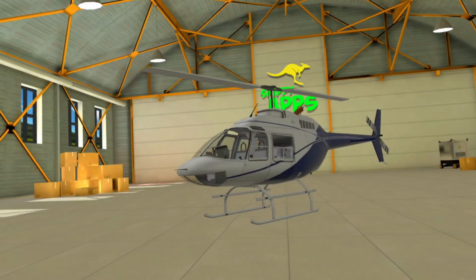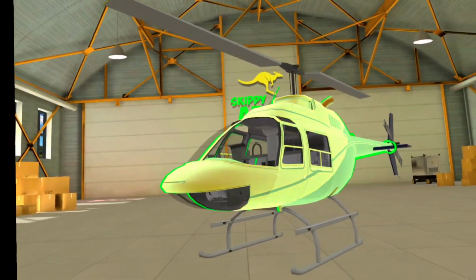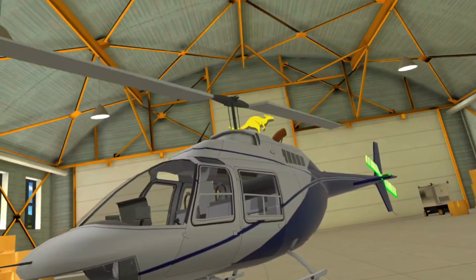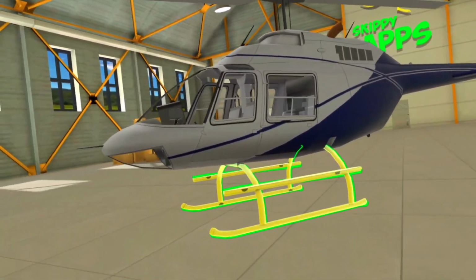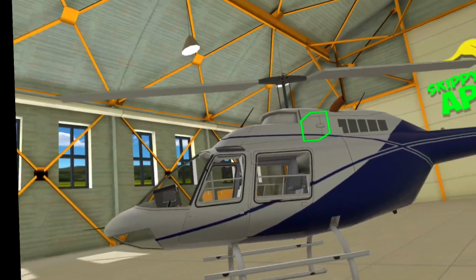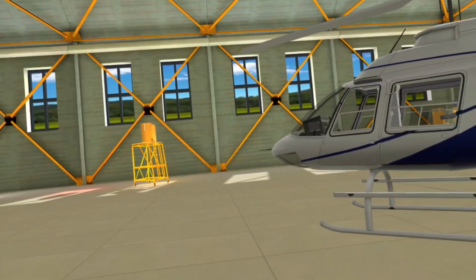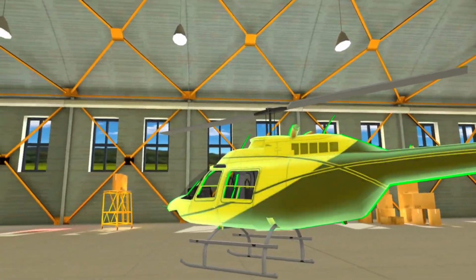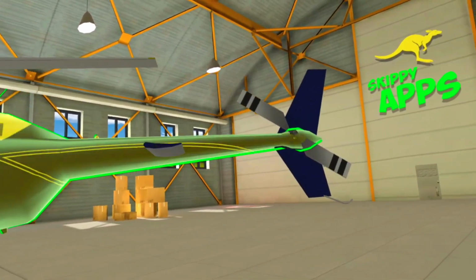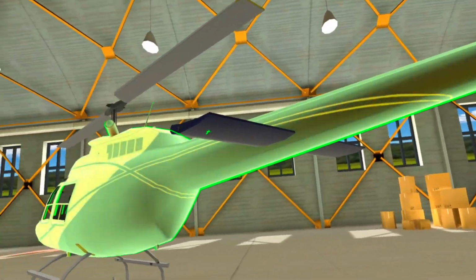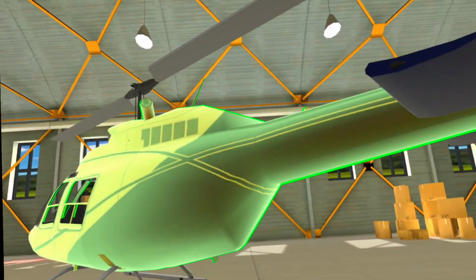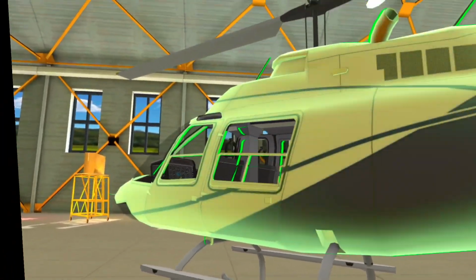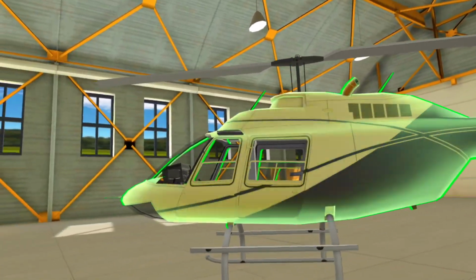The standard helicopter is composed of the airframe, the fuselage, the main rotor, the tail rotor, the landing gear, and the power plant. But there are a lot more components involved. The airframe is made of aluminum and aluminum composite materials, as are the outer panels or skin. The airframe and skin are lightweight but strong enough to support both the engine and main rotor with associated components, which take up the entire area above passenger, crew, and cargo areas.